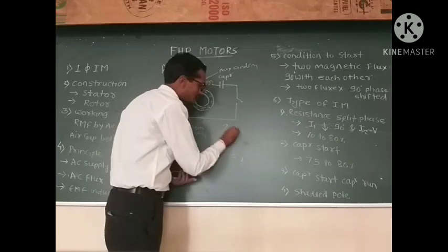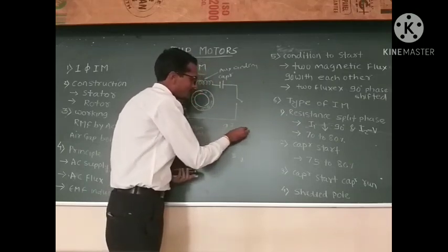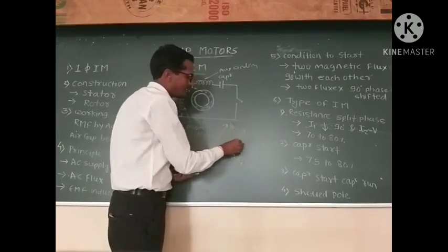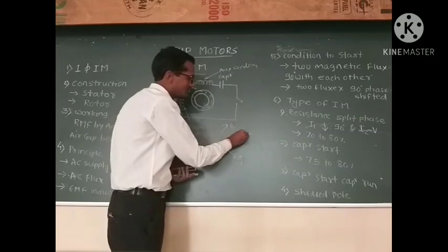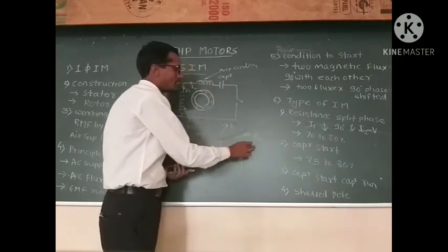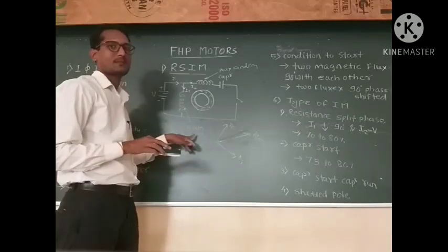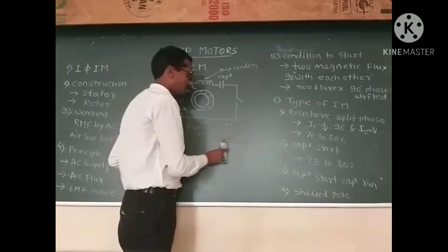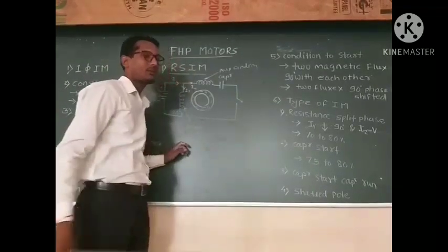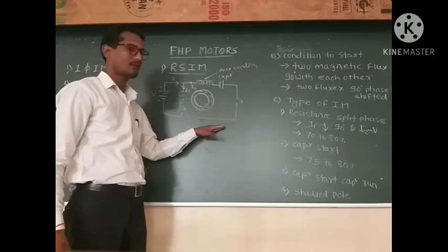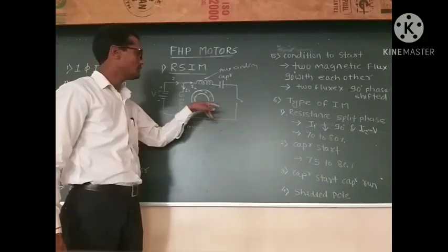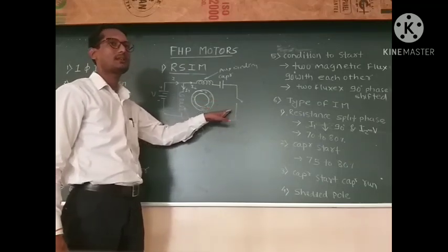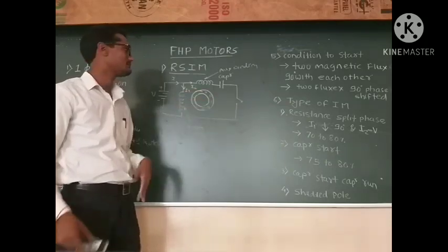This is the I1 current, this is the I2 current, and because of that Phi1 is produced, and Phi2 is produced, and the resultant of these two fluxes produces torque. This torque is responsible for the rotation of the single phase induction motor. This type of induction motor has a very good power factor. So preferably this type of induction motor is used in industries or the power sectors.